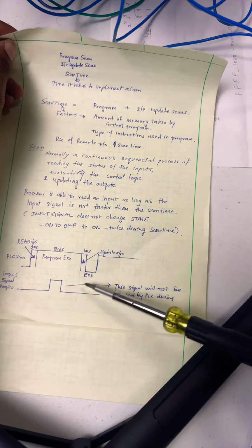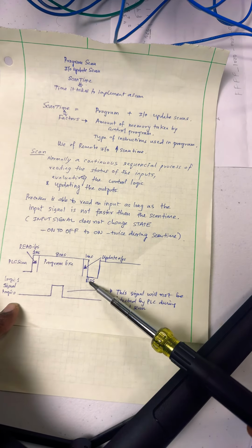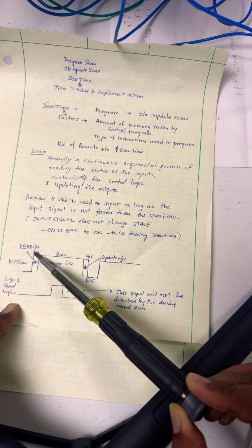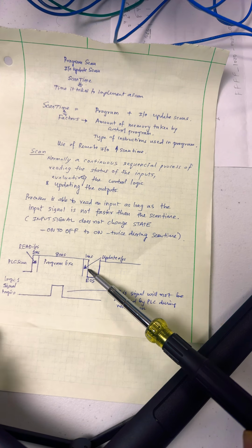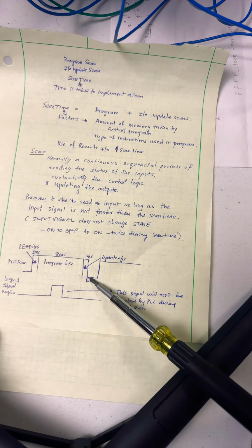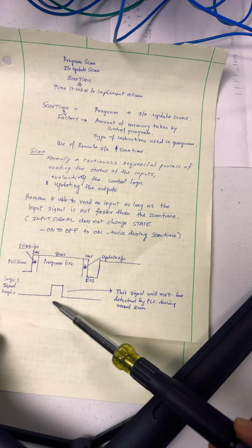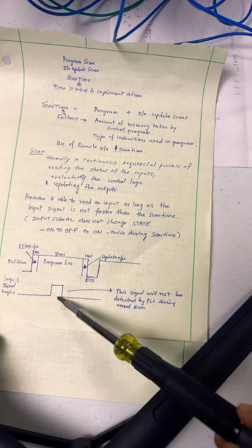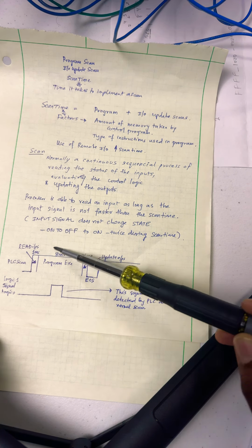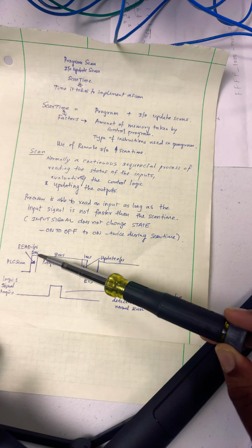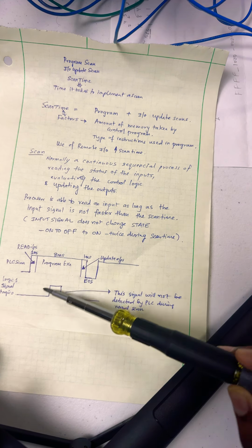scan time. For example, if you look at this, this is where the PLC started scanning. Total scan time is 10 milliseconds. The 1 millisecond is for input scanning, 8 milliseconds is for program execution, and 1 millisecond is for the output updates. And then we have an end of scan signal. For example, if an input signal changes like this, this signal will not be read because the PLC is busy running the program execution. It was looking at this time period for inputs, but the input is here.